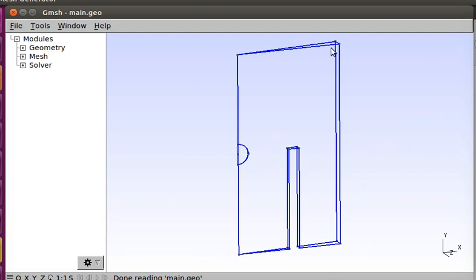Yeah, so as you can see, it's a simple wedge. So physically, there's actually a circular fence with a spherical high pressure source in the center. So a very arbitrary setup, but a good starting point if you want to simulate blast wave propagation. And all the boundaries are set as walls.